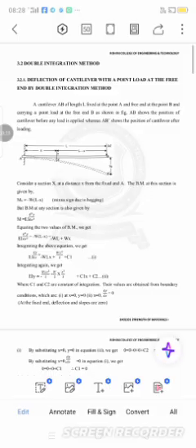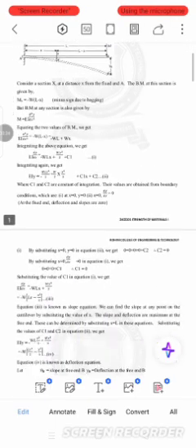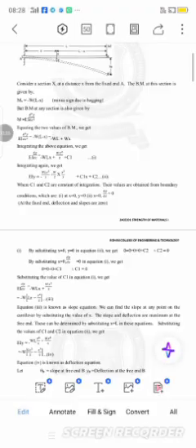Okay, this is the diagram. W is the load. It is acting at the end of the beam. The deflection will look like this. Then, when we take the moment at point x, the load W into the distance is L minus x. The bending moment at any section is given by EI into d squared y by dx squared.